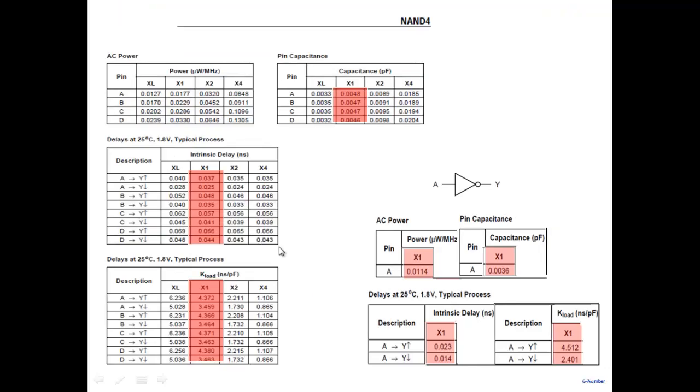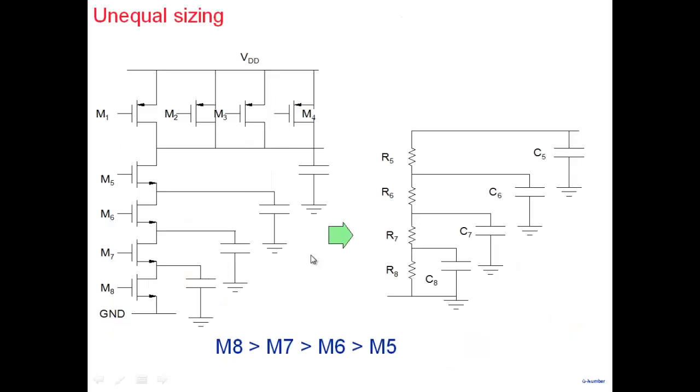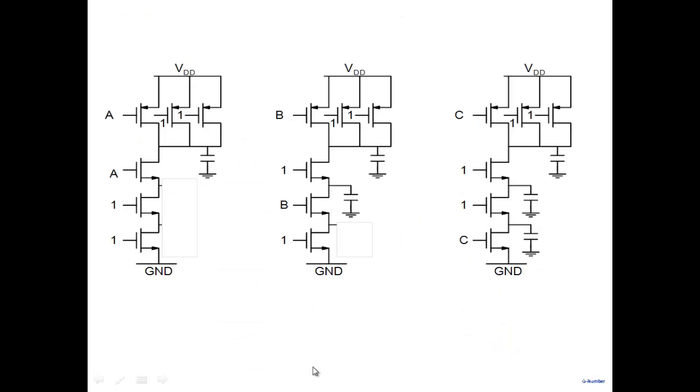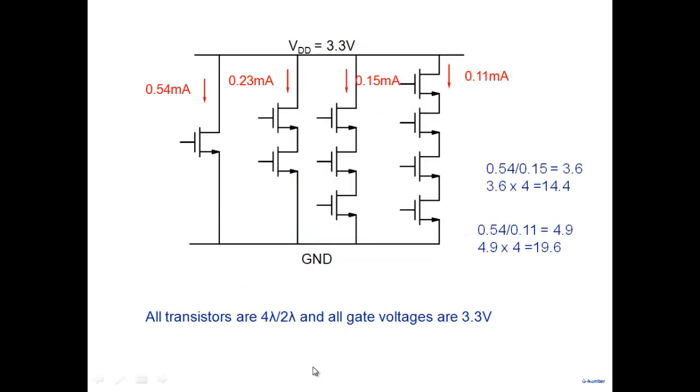All right, so again, I'll leave it for you to look at NAND 4, what is happening here. But as I said, we basically stop at NAND 4. You won't find people making NAND 5 and NAND 6 and all that, for the reasons that you see in this particular case. Either the drive strength goes down, or the sizes become very, very large. So both ways you start suffering. Okay, so you don't do that. Plus, noise margins: you can begin to see what would happen to the noise margins. In this case, how many VTCs will you get when I have 4 inputs? Try and draw, maybe in the next assignment we'll ask you to do that, how many different VTCs and where they are.